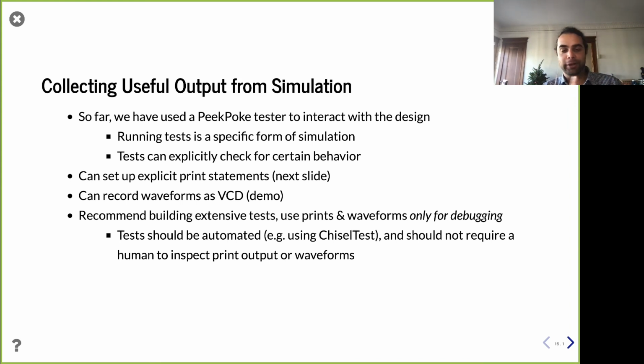Same thing for waveform. You don't want somebody to say, is my module correct? Well, just run it, open the waveform, and look at what value is there at this time cycle. No, that's not a test. That's just a simulation, right? So to me, tests need to include some amount of automation, to let you know if you have the right answer or not. Prints and waveforms are great for debugging, and we're going to cover them in just a second, but do not use them for testing. Testing should be like a proper test bench. And fortunately, we have ChiselTest, which is great, and so we'll just use that.